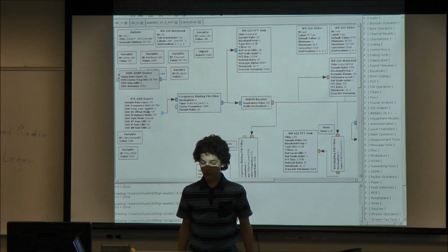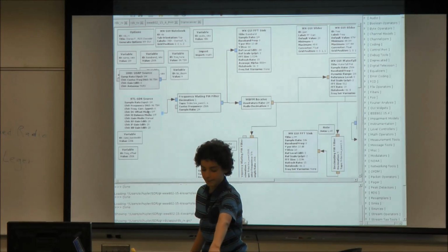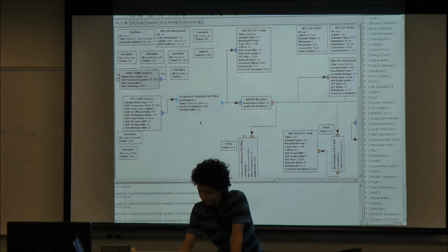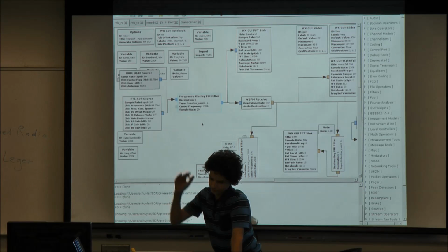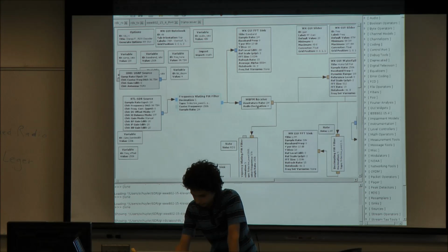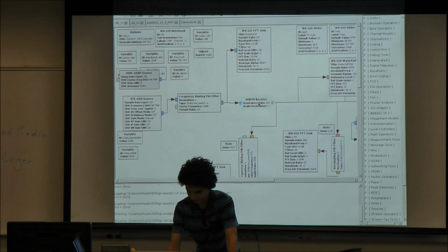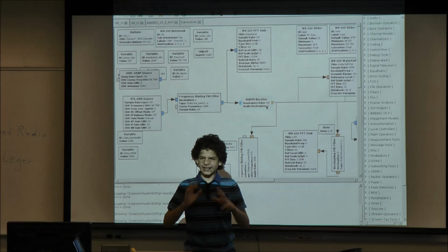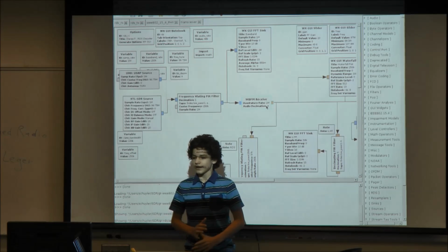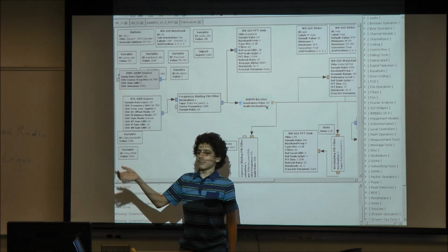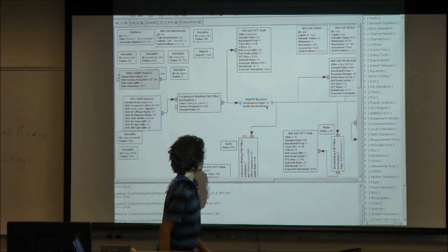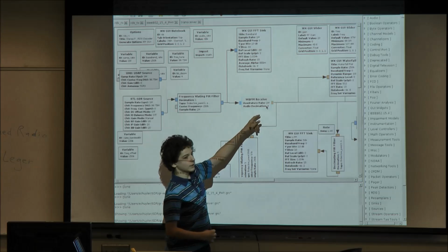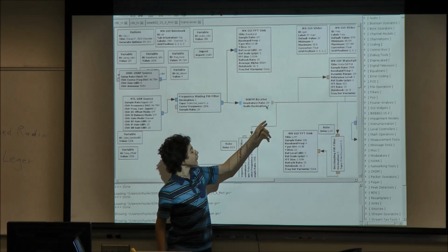Essentially what happens is, here's your source, so data coming from the antenna in the dongle. This is a filter that, in this case, might be doing some frequency translating. Here they're demodulating the FM signal, and you see audio decimation, which is not as cool as it sounds. It's really just dividing the samples so they're 4 times slower, so it goes from 1 megasample per second to 250 kilosamples per second.